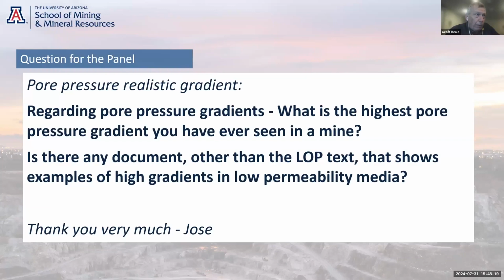But you do get major pressure gradients across structures, and I've seen probably 30, 40 meters of head gradient over small distances across structures. In terms of low permeability media, clay type media, you don't normally get that higher gradient. The higher gradients you get are either where you have stress loading or where you have discrete structures. So in a low permeability media, yeah, you get gradients, but they're not normally that high.